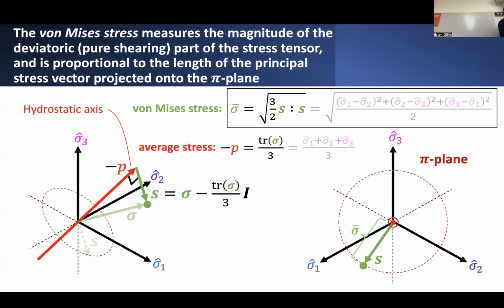So it stands to reason that we have materials that exhibit elastoplastic behavior, but they only influence the deviatoric or shearing part of the total stress in the material. And if we further have a way of measuring this total magnitude of shear stress through a single number, the von Mises stress characterizes a value of shear stress that is always just a single scalar, and it's always greater than or equal to 0. Those are some interesting and nice properties.